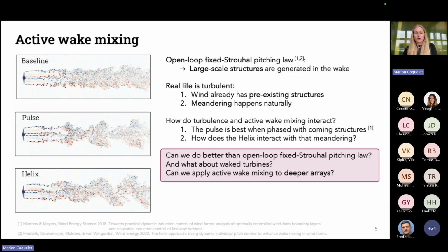At some point, you will come down to the fact that you need to know the wind. And you have several options. The most basic one to know the wind that is impinging is probably to use an anemometer, but that might be a little poor in terms of the information you get. The other one, if you're lucky enough, you might have a lidar mounted on the nacelle, and then you get plenty of information. It's very comfortable.